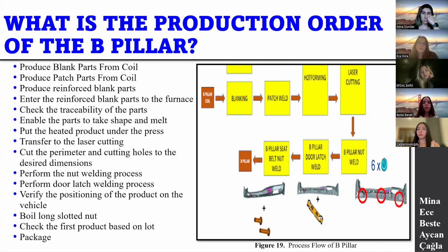Perform door latch welding process. Verify the position of the product on the vehicle and weld the long slotted nut. Check the first product based on lot and lastly package.